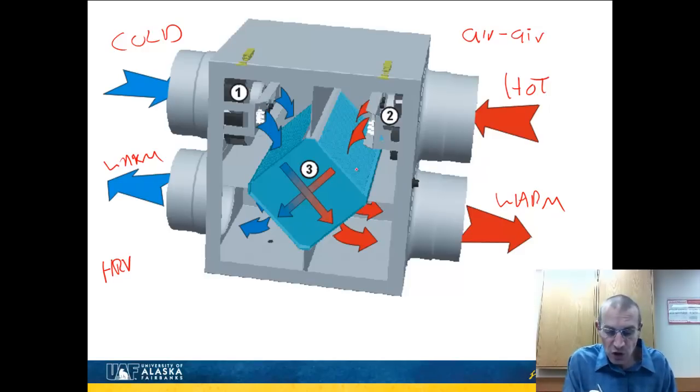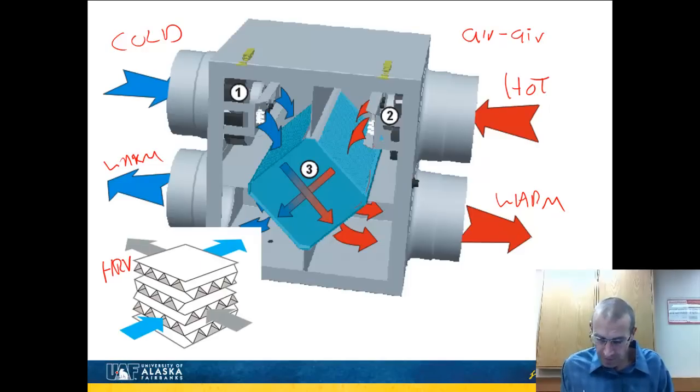And so the exchange goes on inside this little honeycomb unit here. And what they look like, I kind of show on this diagram here. It's this sort of tessellated or honeycomb. You can imagine if this is the warm air shown in the gray and the cold air in here. Again, they don't mix, so one fluid will be going through its own channels and the other fluid going through its own parts of channels. And the heat transfer is occurring across these really thin plates.